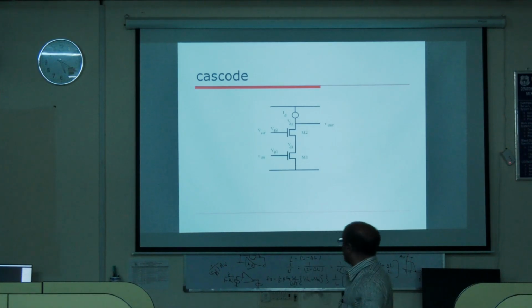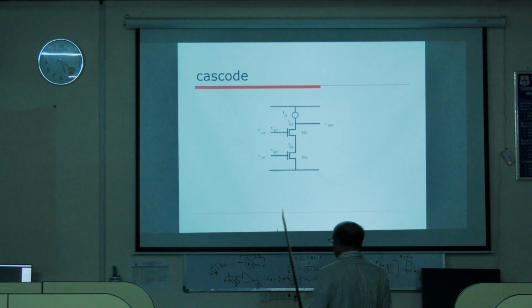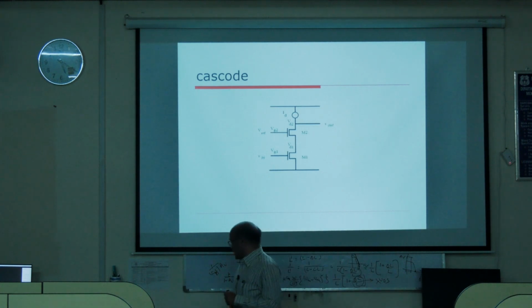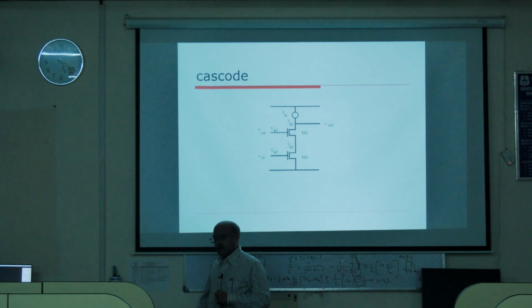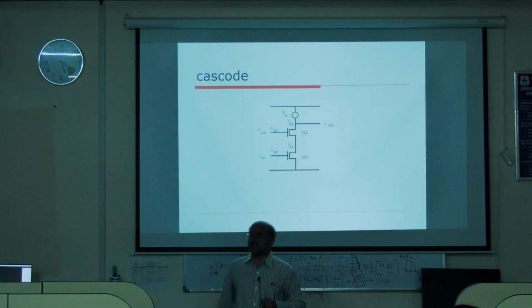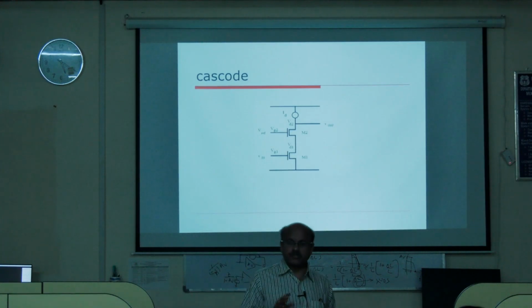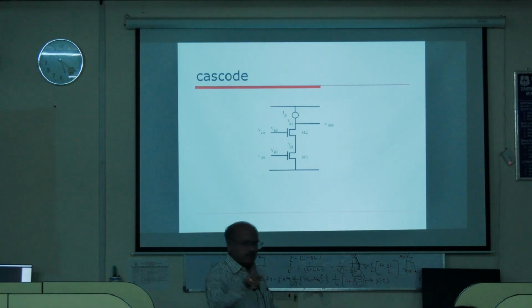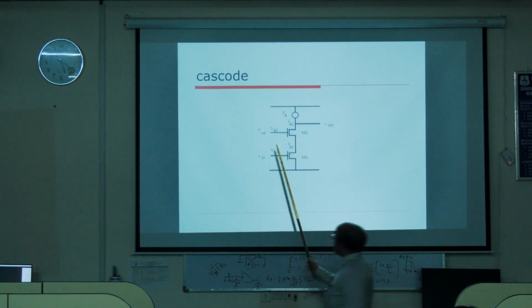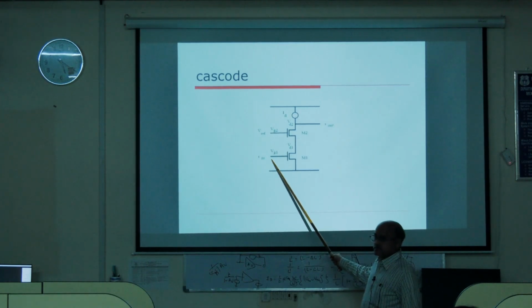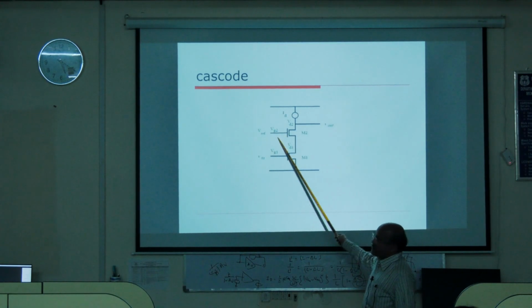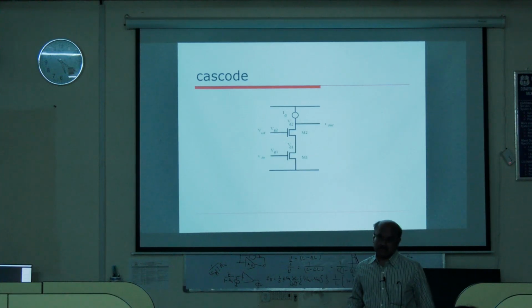Okay. So here you can analyze once again. Remember these two transistors are in series, therefore the current through both of them is the same, right? We will analyze it with a small assumption. Let us assume that there is a fictitious transistor, because here, please remember, the signal is applied here only. Here I am giving only DC.